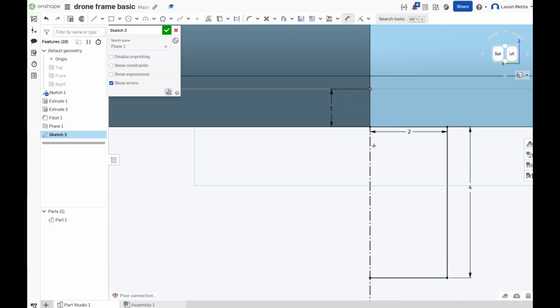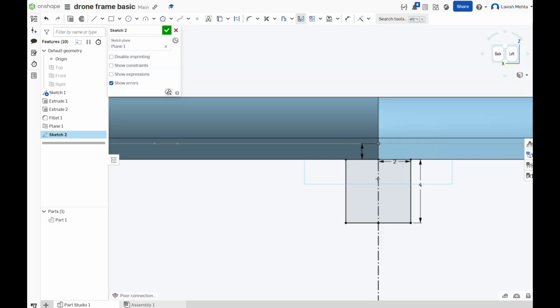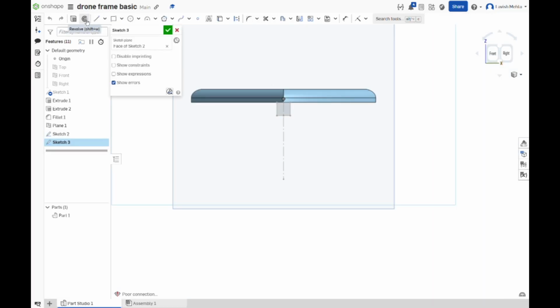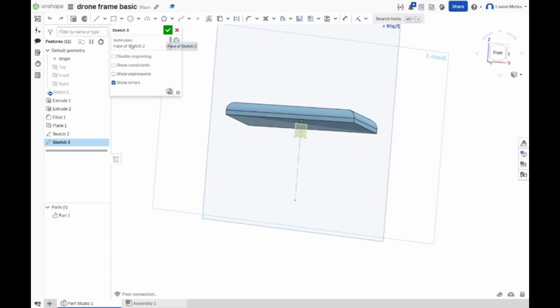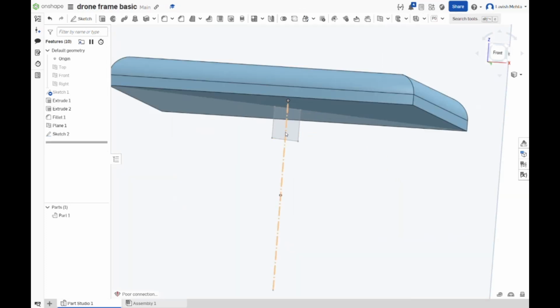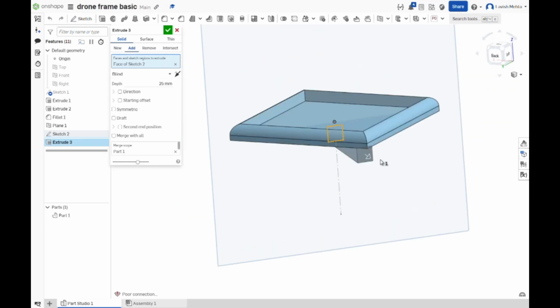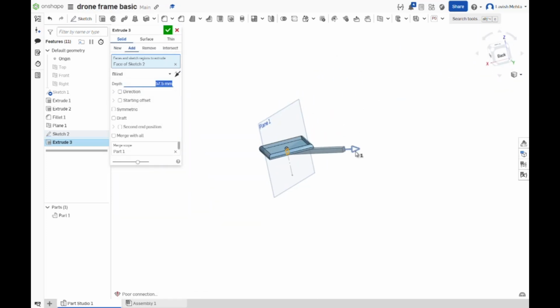Once you did that, choose the mirror tool once again. Select the mirror line and mirror all the specific dimensions. Since the closed geometry has been generated, I will just choose the highlighted area and choose extrude, and now you can see that the arm has already been generated.